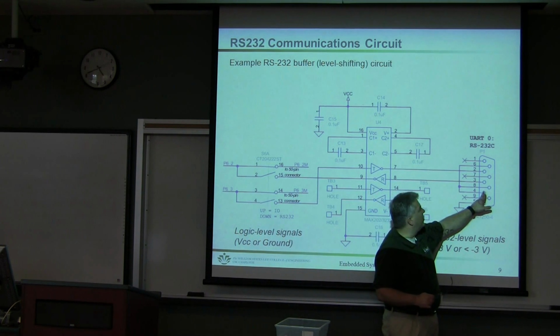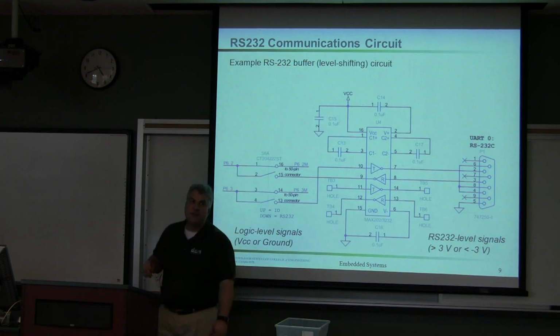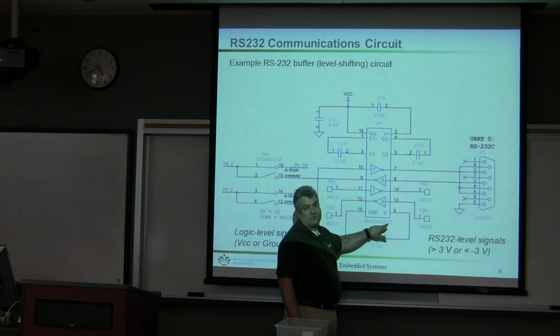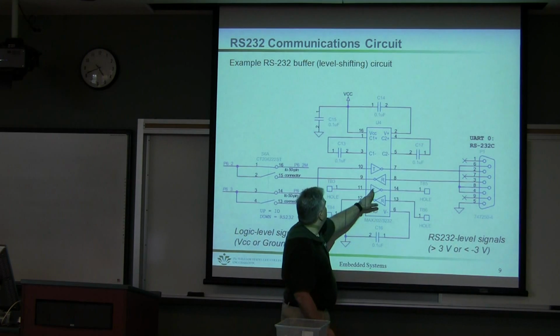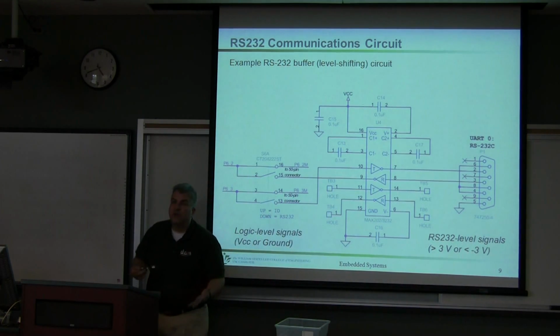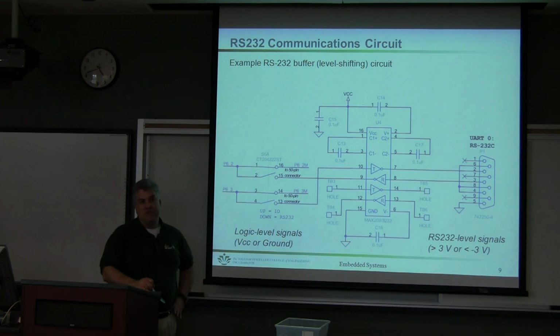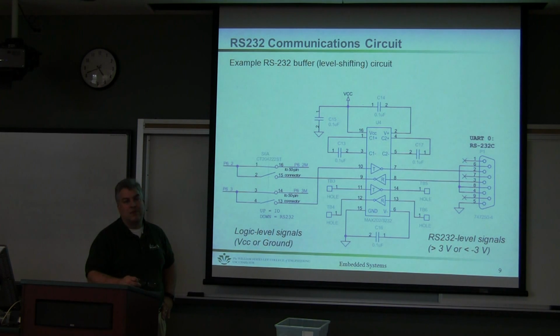But you have to make sure your voltage level is going to be appropriate for the PC to read. Now at the other end, the PC is going to have a 232 chip as well, which will then convert the signal it's receiving into a voltage level that the computer at the other end can actually work with. In this case, your typical PCs will have an internal bus, and it'll work probably somewhere between 3.3 volts and 5 volts at that end.